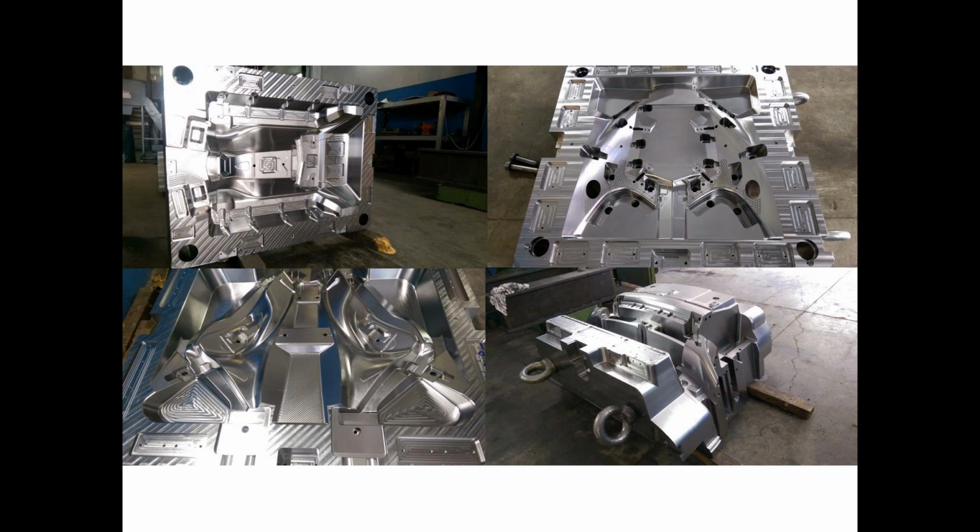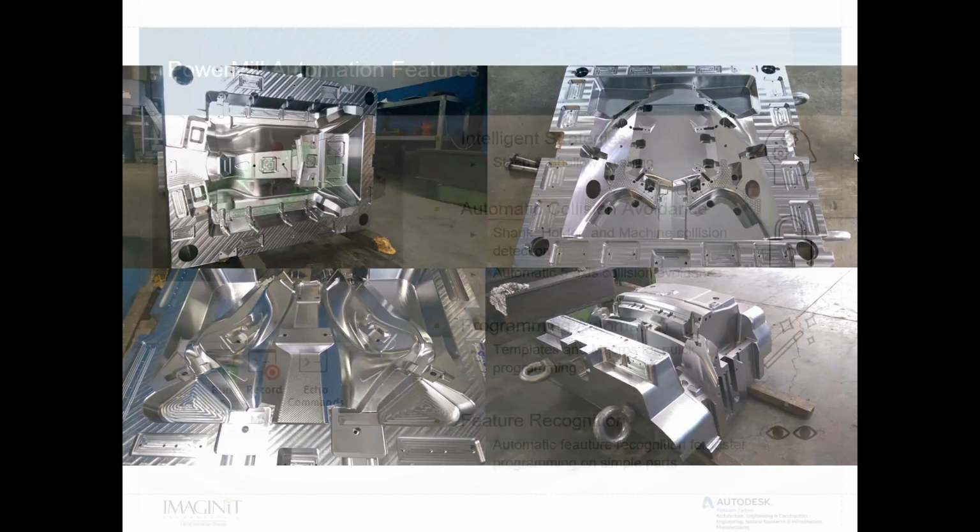So with these types of parts, could you get there with something like Inventor CAM? Potentially, but you're going to have a hard time. It's going to take a long time to program. And also, you're not going to have that confidence. You may not be getting the surface finish you need, and it may not be safe to run because you can't do that full machine simulation. So these types of parts are going to run well with PowerMill.